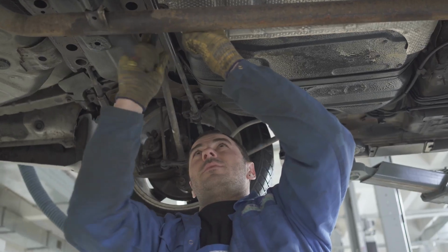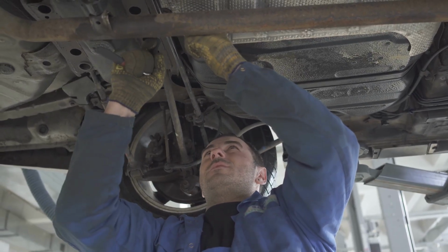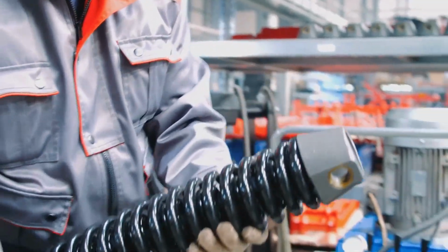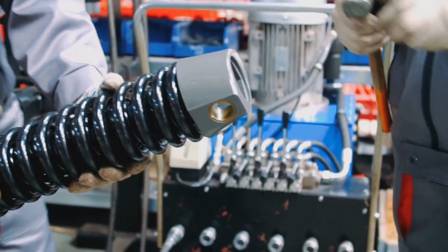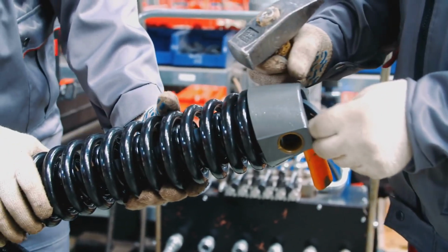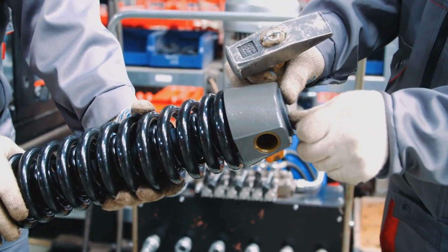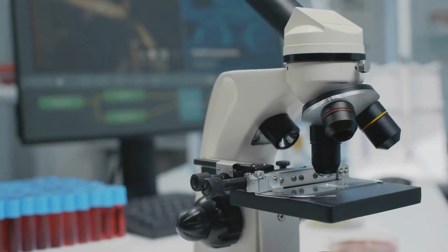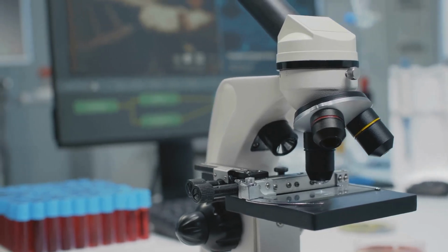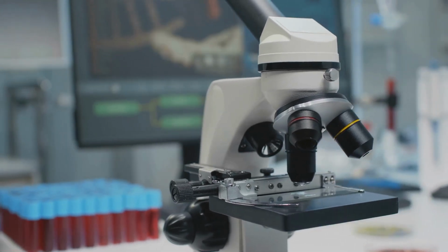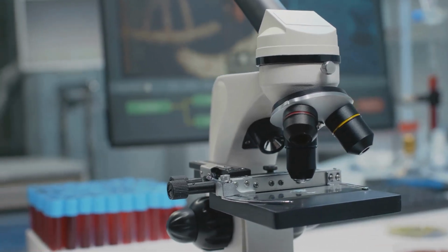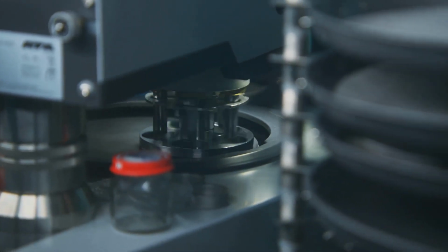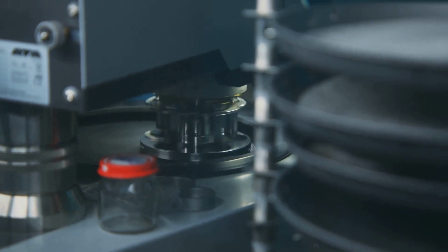These experience significant cyclic loads, often with stress concentrations that lead to local plastic deformation. Using the epsilon n method allows designers to optimize these parts for durability, reducing weight, while ensuring they can withstand the harsh conditions of daily driving or even extreme performance. It's about understanding that local microscopic yielding, which the SN curve might miss, but which the epsilon n method captures, provides a more robust and reliable design prediction for these critical applications.